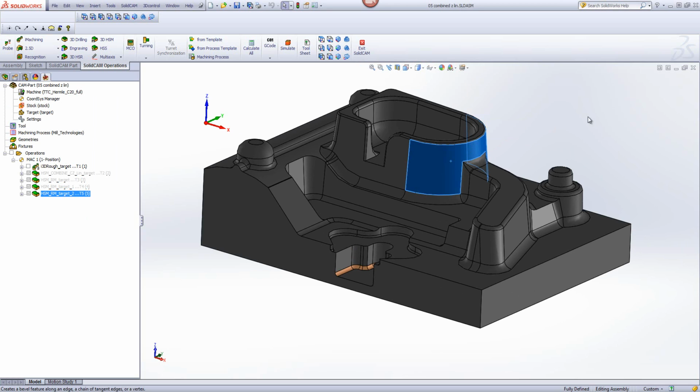The walls are actually angled, have a pretty steep angle, whereas these floors over here actually have a pretty shallow angle, and these are also pretty shallow over here as well. And I've seen a lot of people still using two different operations, where they would first do a constant Z, because constant Z works beautifully on these steep areas, but does not work well on shallow areas.